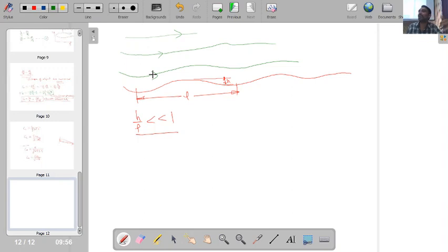So it means that whatever analysis I presented for the aerofoil case in the previous slides is applicable only for small angles of attack, because if you go for large angle of attack, then our perturbed velocity values will actually be large in magnitude. If these are large in magnitude, then this linearized theory of small perturbations cannot be applied. Okay. So similar is the case for this wavy profile also. We are assuming that our wave amplitude is small in comparison to wavelength, so whatever flow perturbations exist will be small in magnitude. Okay. Is this point clear?